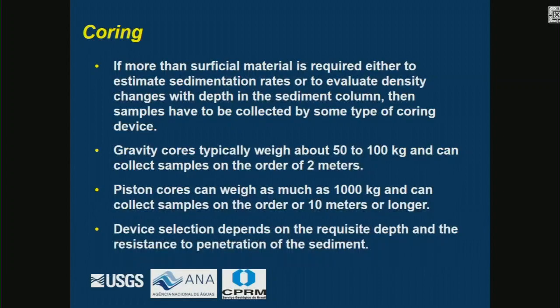All right, if there's a lot of sediment and you need more than just a surface grab, coring is an option. There are two different types, the gravity core or the piston core. If you're looking at density, these two are the best. The big difference between the two is that one only goes to about 2 meters and the other goes to about 10 meters.